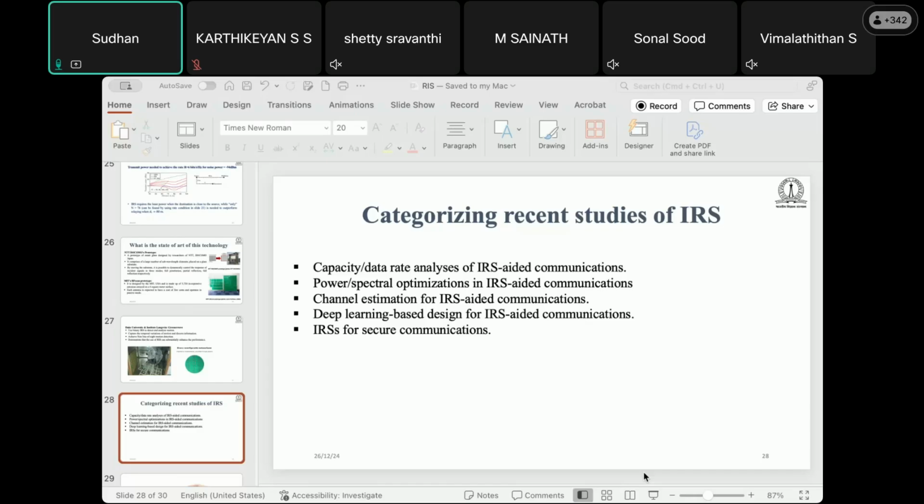So this is Rician fading, or sometimes we can even treat this as a deterministic signal, because the RIS and base station are line of sight, beam focusing is there, and we transmit more power in a particular direction. There are many assumptions; we can directly assume Rician fading.